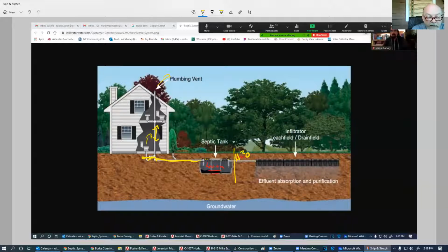So, we've got to allow for this to take place and stop that at that plumber's P so that we have the vents here. But then we don't want to suck these dry. So when this is flushed and water's flowing through here, we want to be able to have air going the opposite way back into the vent so that we end up not sucking these things dry in there. So that is, in a nutshell, what this looks like. So let's go a little bit further.